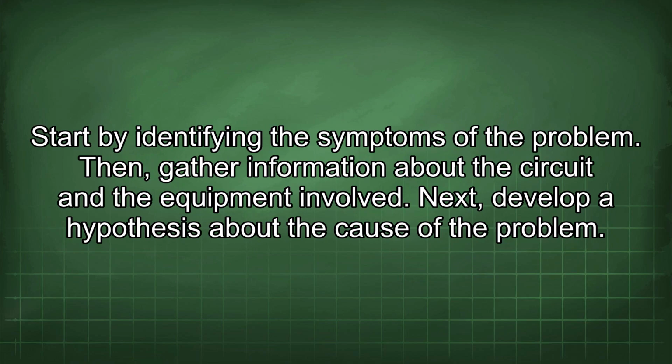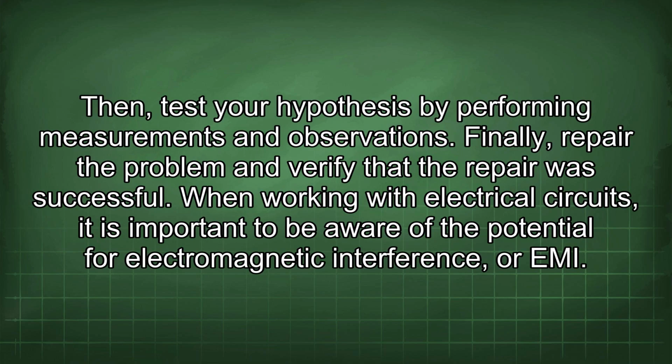Start by identifying the symptoms of the problem. Then gather information about the circuit and the equipment involved. Next, develop a hypothesis about the cause of the problem. Then test your hypothesis by performing measurements and observations. Finally, repair the problem and verify that the repair was successful.